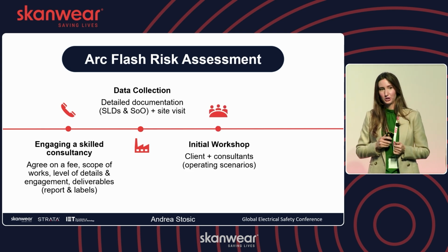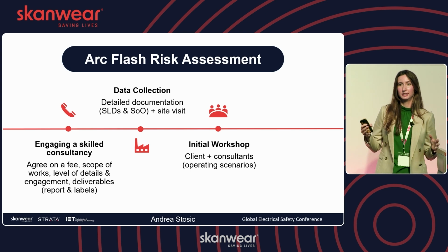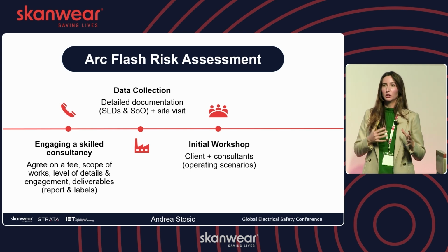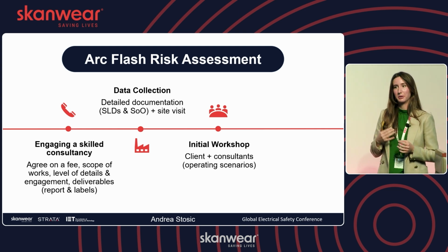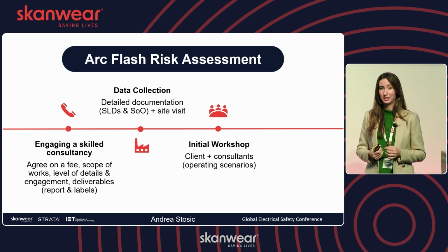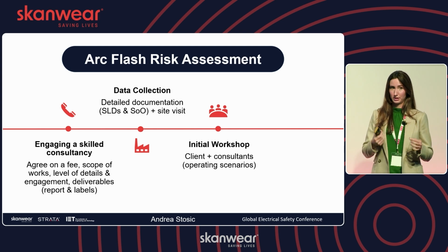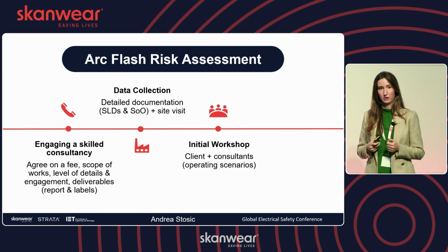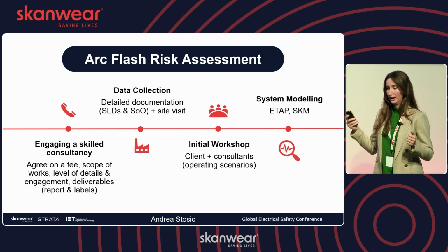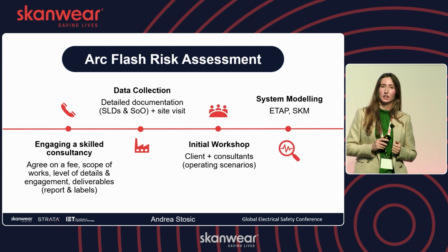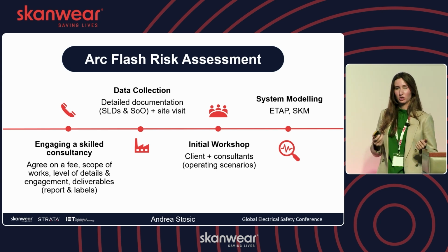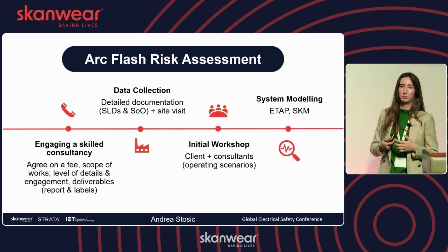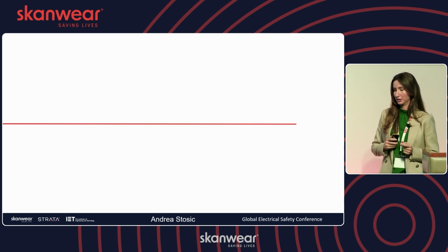Then I propose an initial workshop, basically to identify any gaps, to discuss the information shared, and to discuss the sequence of operations, making sure that the consultants understand how this site operates, because this will be critical for them to set out operating scenarios in the software that they're using. Then they get started with system modeling, and typically they'll use ETAP or SKM, which are the two most well-known software packages that originate from the US, but are broadly used across the world.